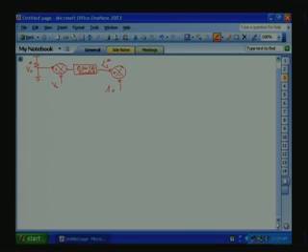This is your feedback, then your current controller. Current controller, what we got? This is a proportional gain only you require. So, what we got here, it is equal to K1 is equal to L divided by Ki G into T. T is the first order lag. G, this will go to our converter.